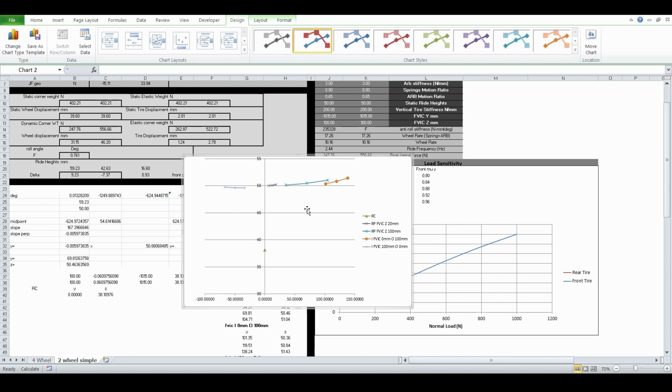And then compare that for the same suspension. It calculates the roll center to be right here at about 38 millimeters up and on the center line. So we're showing that's the roll center. It's not actually rolling about the center. It's rolling pretty far off from it. So it's showing that the roll center isn't the center of rotation of the vehicle.